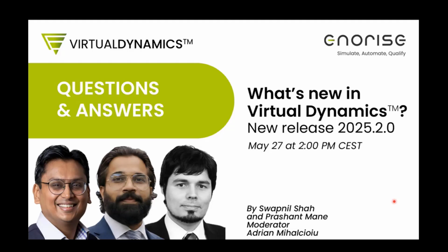It's a very interesting question. We have also thought about it. This synchronizer does not add any additional inertia to your model, which means that if you're using this analytical gear synchronizer, the inertia of this entire mechanism, the synchronizing mesh and the ring as well as the gear itself, is all already provided in the gear inertia. So in that way it is not required.